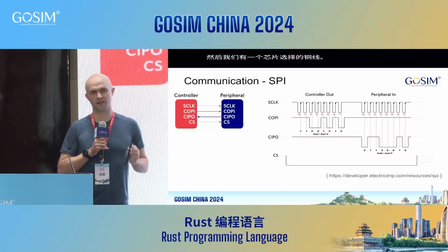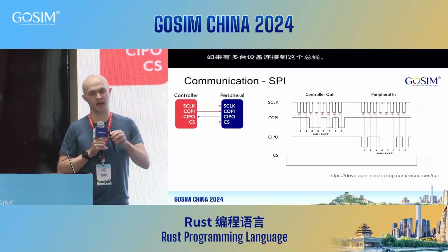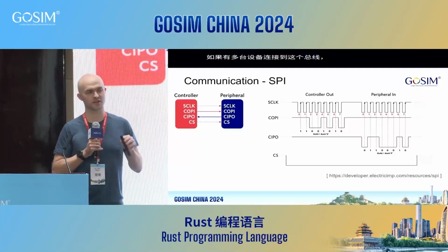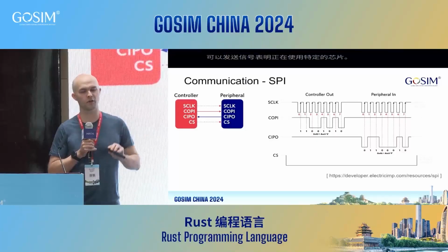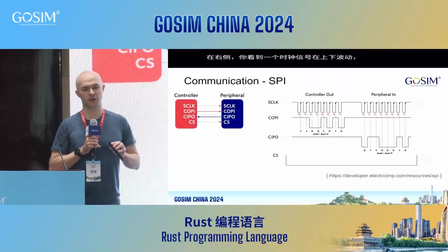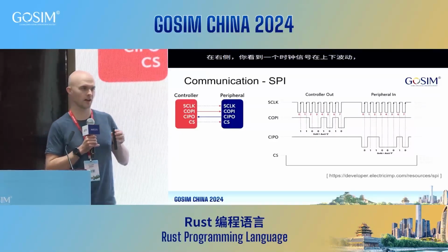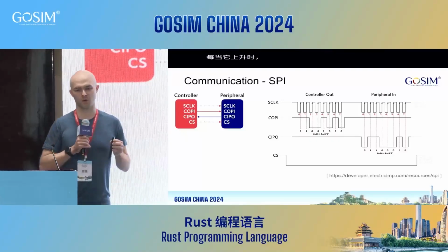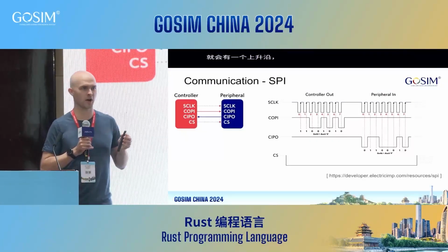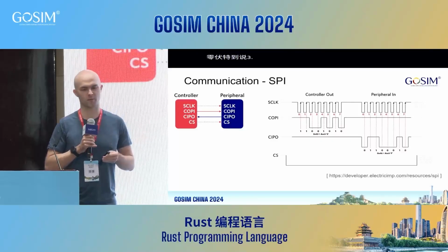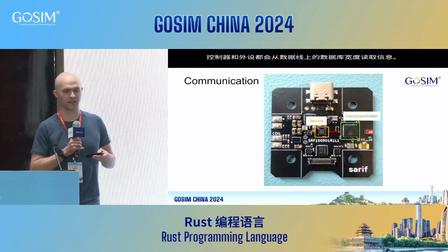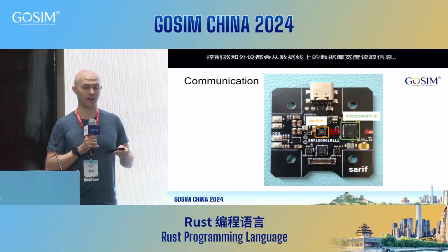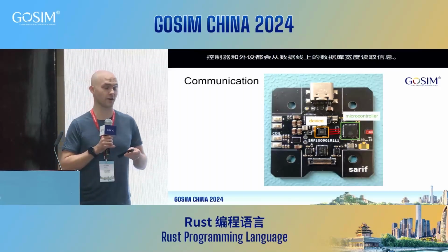Concretely, on the right, you see a clock signal going up and down, and every time it goes up, so you have a rising edge, going from 0 volts to say 3.3 volts, both the controller and the peripheral read from the data bus what's on the data line, and keep that somewhere in memory and pass that over to the processor. So we do not have one copper line. We have either 3 or 4 copper lines if we have SPI.